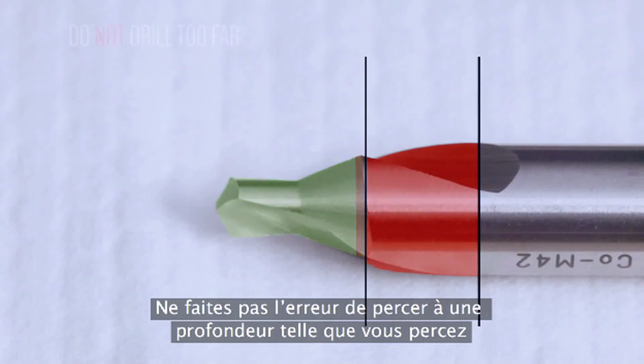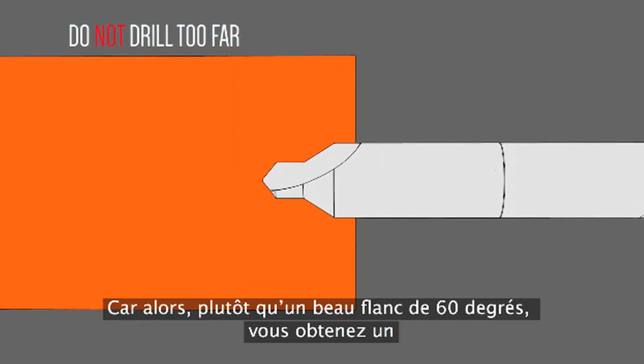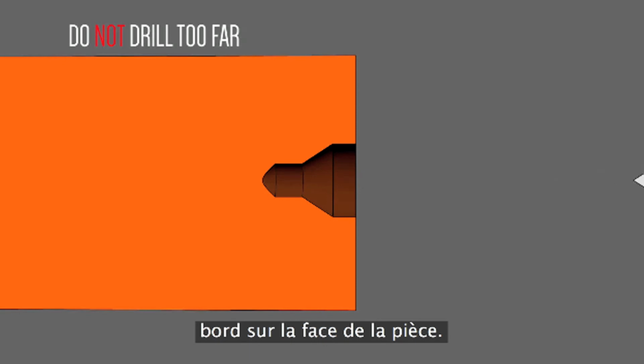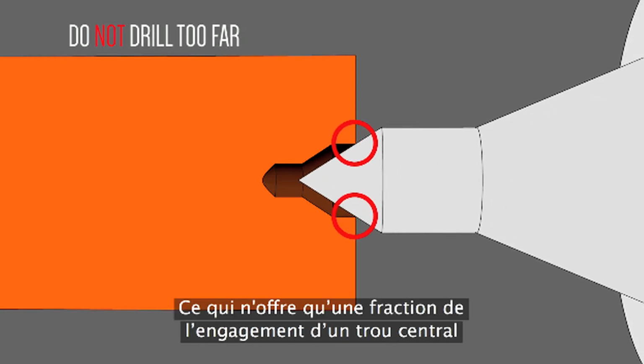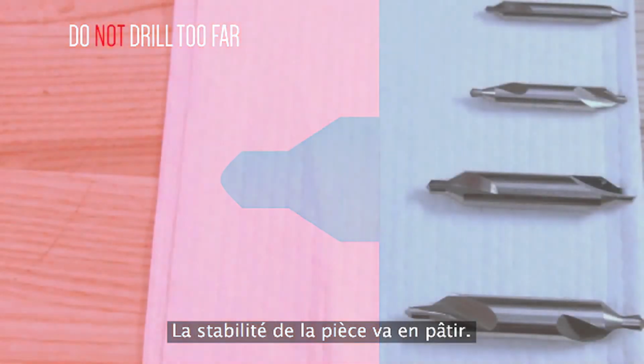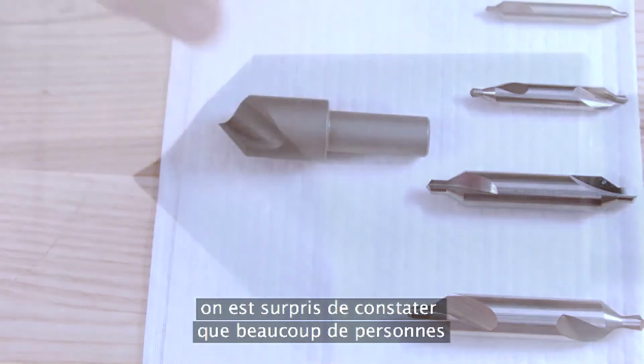Don't make the mistake of drilling so deep that you drill into the major drill diameter. Now, instead of a nice wide 60-degree flank, you'll be left with an edge at the face of the part, which will only offer a fraction of the engagement of a properly drilled center hole. Part stability will suffer.